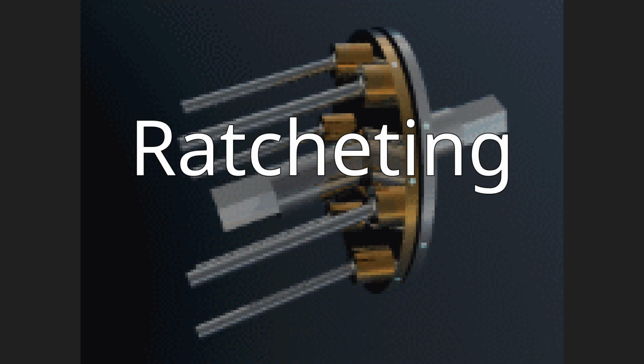Ratcheting. A ratcheting CVT uses a series of one-way clutches or ratchets that rectify and transmit only forward motion. The on-off characteristics of a typical ratchet means that many of these designs are not continuous in operation, i.e. technically not a CVT. Ratcheting CVTs can transfer substantial torque because their static friction actually increases relative to torque throughput, so slippage is impossible in properly designed systems. Efficiency is generally high because most of the dynamic friction is caused by very slight transitional clutch speed changes.